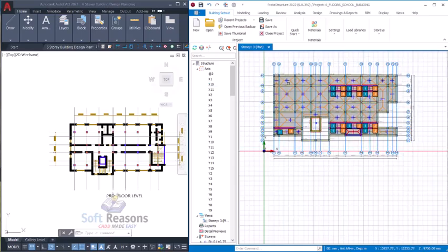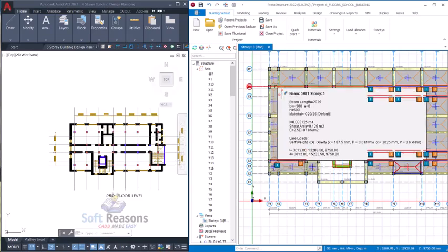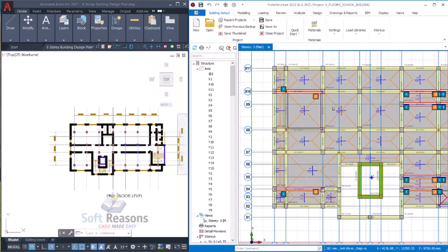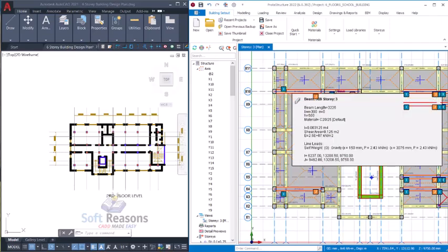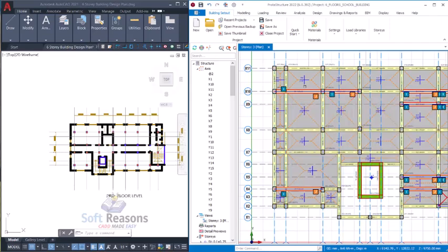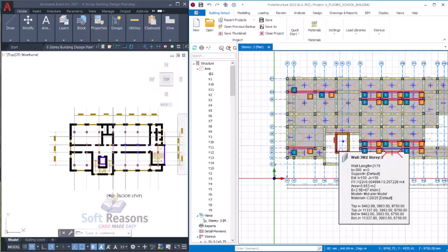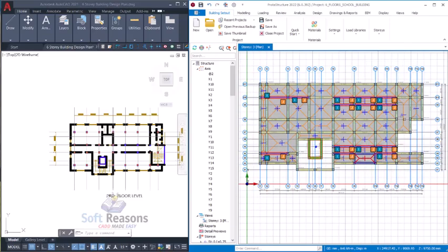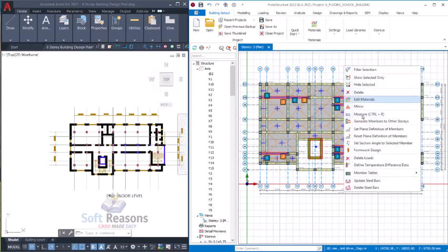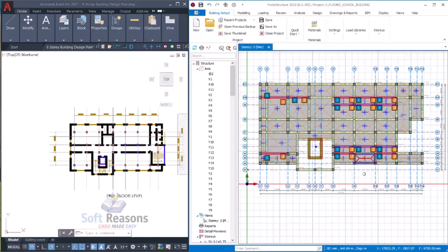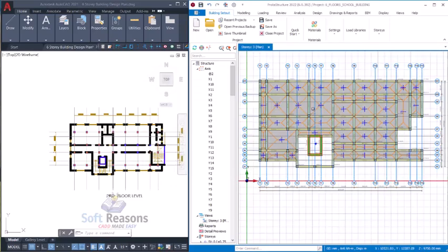Alright, also this beam here, we will get rid of wall load on that one, and as well this beam successfully. So you have to check critically to actually get rid of wall loads on the beams that are not supposed to carry wall load. So delete options, OK options to have this just like this.